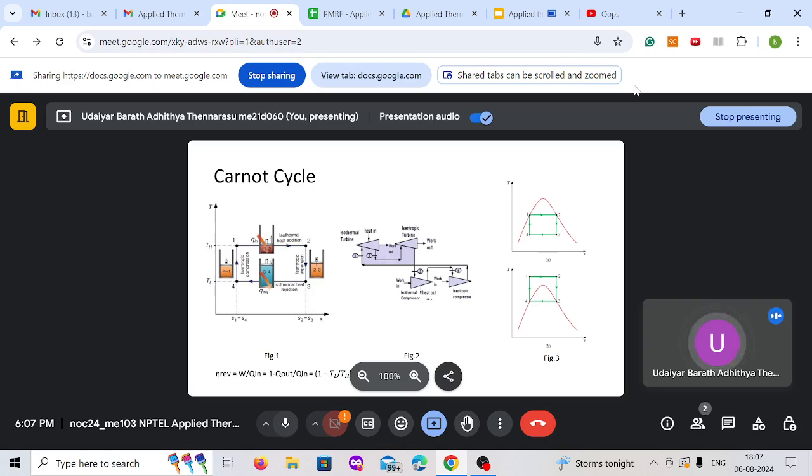Having a two-phase in your turbine, so that will have a different velocity, so it impedes the turbine blades and it can damage them. So there will be another set of problems arising because of having a two-phase fluid. So these all limit the use of a Carnot cycle in a practical system.